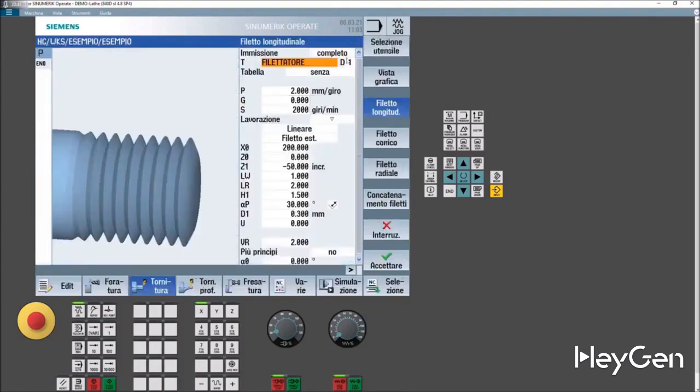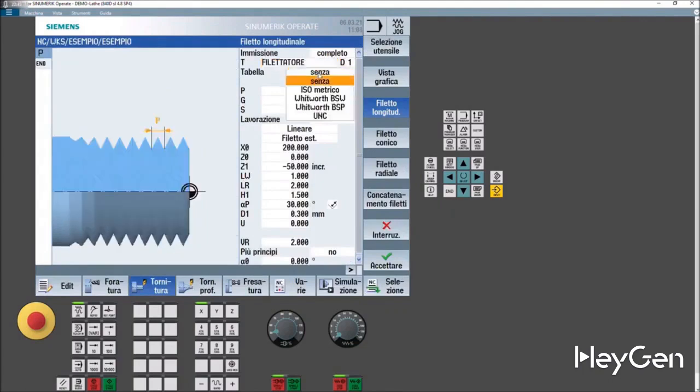So we transfer to the program, and it's very simple here too. Do we want to use a table? Do we want to use an ISO table? Are we getting to M100? Let's see. We're not getting there, so having to thread on a diameter of 100, we work without a table. Let's do a diameter of 100, with a pitch of 4.